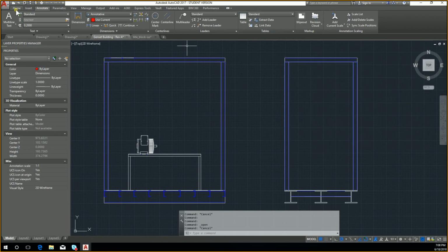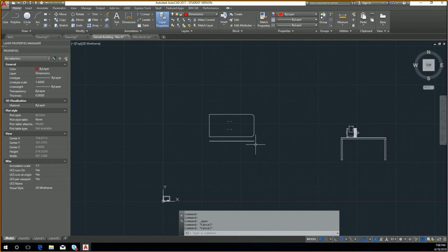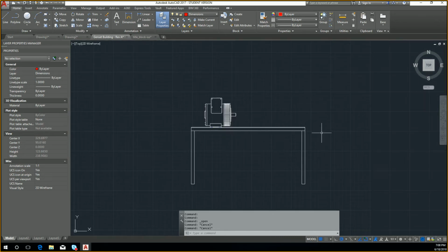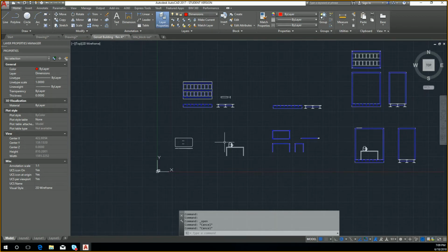And some of you guys chose to do it this way. You went through and created multiple layers, right? Created maybe 20, 30 layers, so that there was a layer just for your beams, a layer for your table, a layer for your motor. By doing so, you actually may have protected yourself within any changes that could have happened, because you would only be dealing with one model space view. Whereas the person that perhaps did it this method, I created a table here, and then I created a table and motor assembly here. Right there, you can already see the problems. I modified the one view, but the next view is not changed. So this is already the broken link. So this is more about drafting concepts, right? Drafting concepts and how they can affect your revisions.